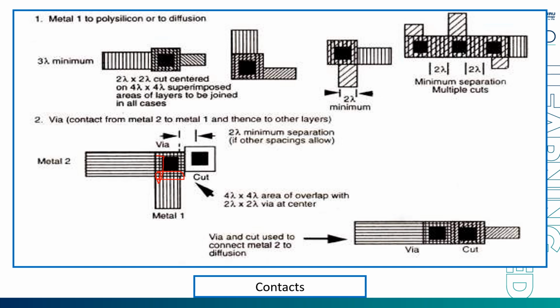You might wonder how to follow such minute rules. All these are automated. Once you design the front end part and go for the back end, once you are done with the layout connections, that is once you map your layout, when you give a design rule check, all these design rules will already be there. When you check, whatever is not satisfied will give you an error. You can just go over it.